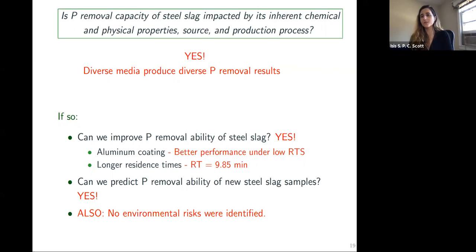And we have structures that are built that way, directly in the ditch. But what I would say is that we look for hotspots of phosphorus in the field. Once we are already in the ditch, we already have that phosphorus diluted in all the water that is coming in. So if we treat it before, we have to treat a lower volume with a much more concentrated phosphorus concentration. So that is more adequate for phosphorus removal structures to work at their best.